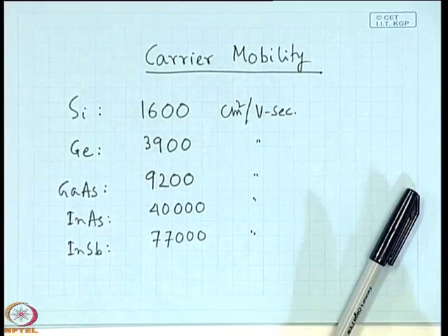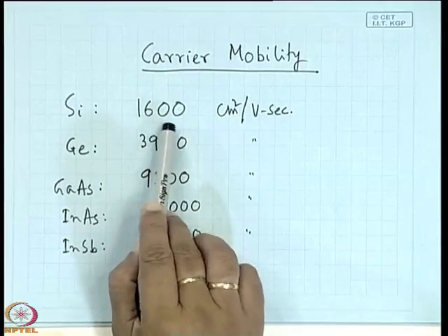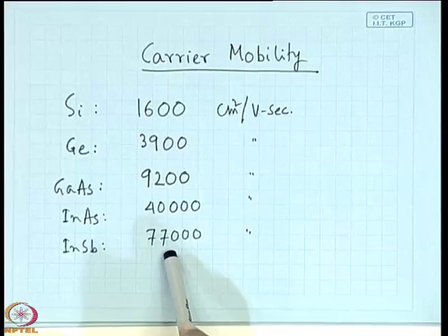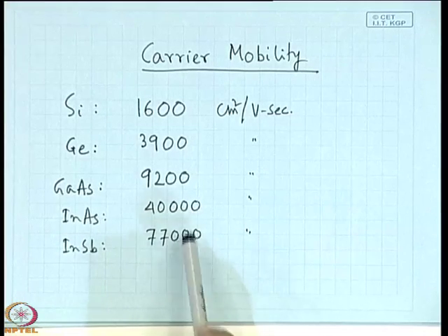because only integrated circuit is not the end. You have different types of devices. One is say laser, LED, detector, then microwave sources, impact diode, read diode, pin diode, etc. Microwave devices are very important particularly for communication, for modulation of signals, etc. So, silicon is not used because its mobility is very less compared to say gallium arsenide or other materials, say indium antimonide 77,000 is very high,